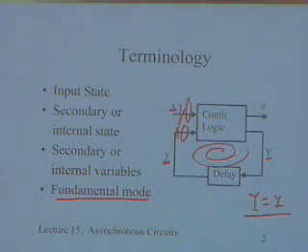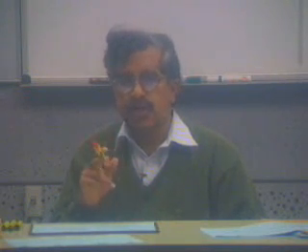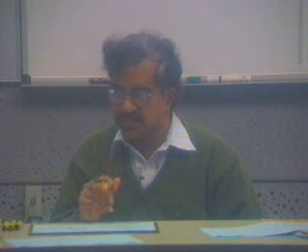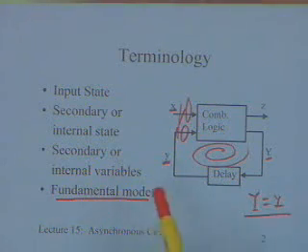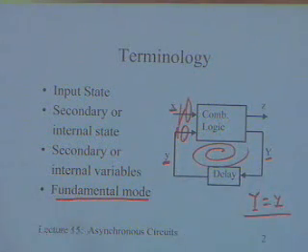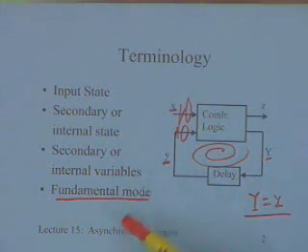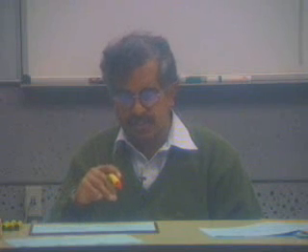Once an input change occurs, first of all, only one input can change at a time. Second, if one input changes, it is going to result in some transients, and the next input change is not going to occur till we reach an equilibrium. During the time these transients are coming, we will not change the state, because then the design becomes extremely complex.